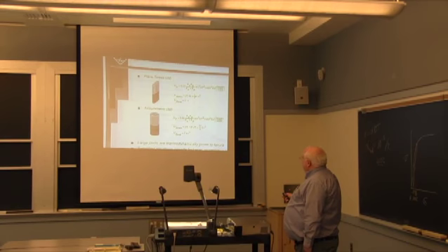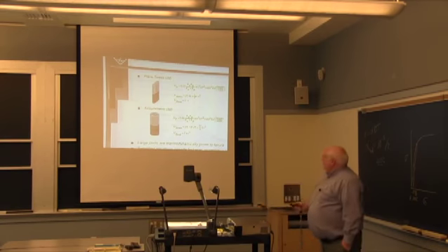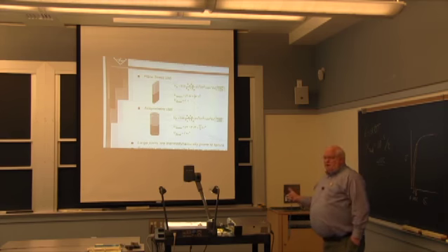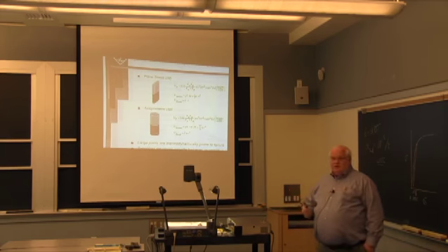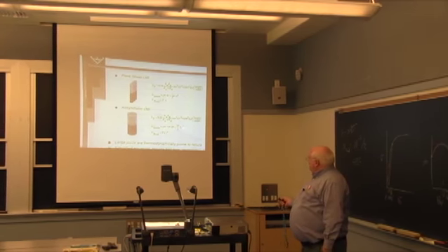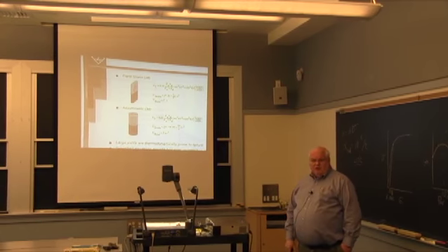The bond energy just goes linearly with the bond area. So it's proportional to the length or the width of this whole thing. Well, if you look at this, you notice the strain energy increases as the square of the length of the bonded area, and the bond energy or strength in force goes as the distance to the first power. And if you do it axisymmetric, you find that the strain energy goes as the third power of the radius, but the bond area goes as the square of the radius in a circle.